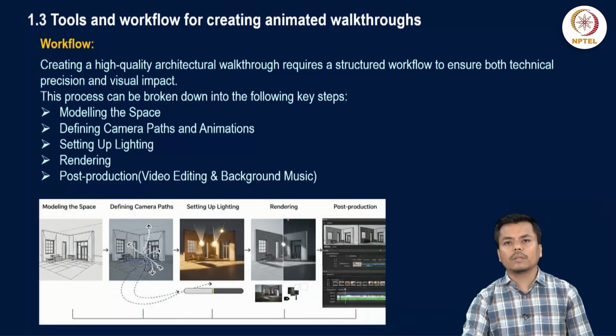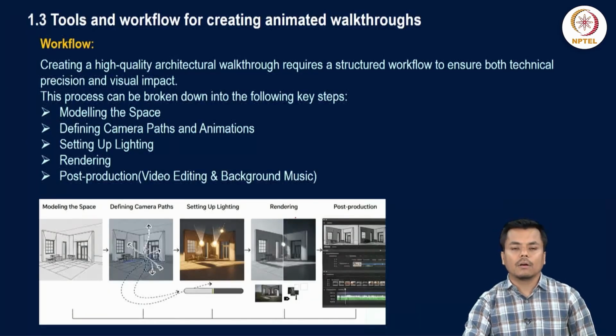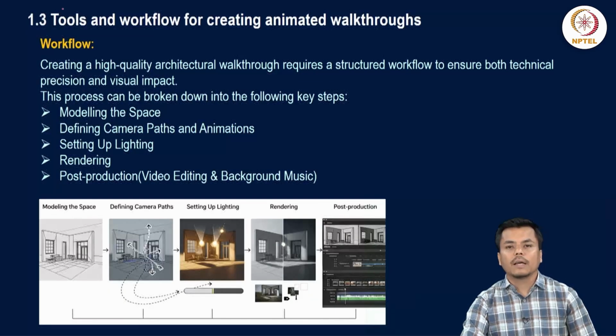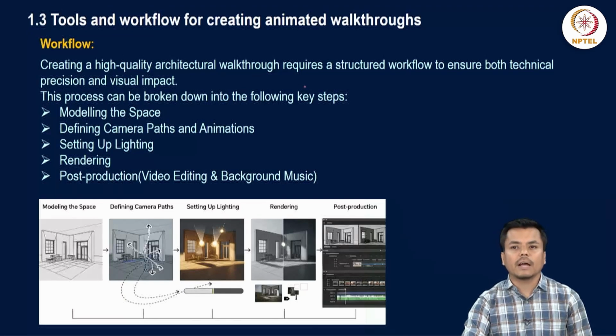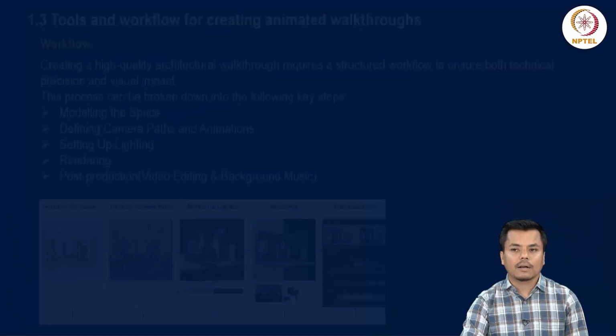The workflow that is essential when you start preparing the walkthrough is this: a high quality architectural walkthrough is only possible when you follow a proper process. For example, it starts with modeling the space, then you define the camera path and animation, set up the lighting, then the rendering process, which type of rendering is adopted, then the post production, that is video editing with some background music. All these are to be considered.